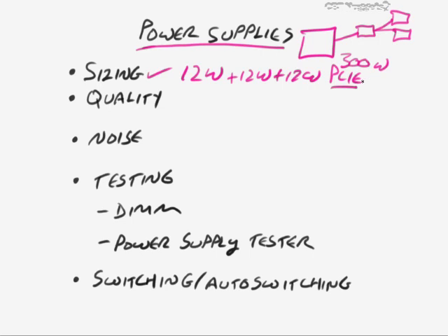Then some of those PCI Express devices, at least theoretically, I haven't seen anything that will do this, but it is theoretically possible that some of them could require up to 528 watts just for the PCI Express video cards. So that's extremely large, especially when power supplies are usually 4, 6, maybe 800 watts on average. If you get higher powered ones, they can get over 1,000. So anyway, you just add stuff up.